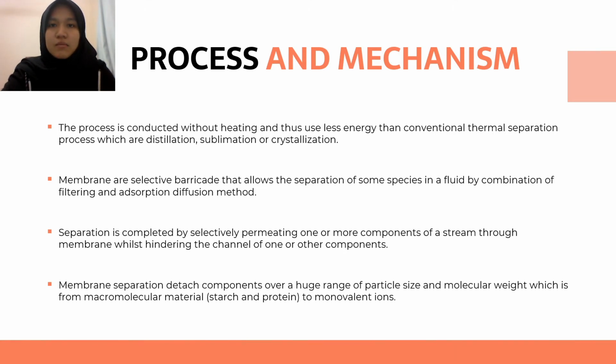I would like to present the process and mechanism of membrane separation. Membrane separation process is very essential in the separation industry. The process is conducted without heating, and thus uses less energy than conventional thermal separation processes, which are distillation, sublimation, or crystallization. A membrane is a selective barrier that allows the separation of some species in a fluid by a combination of filtering and adsorption diffusion methods.